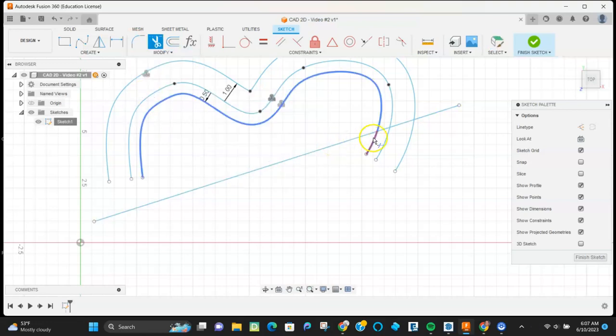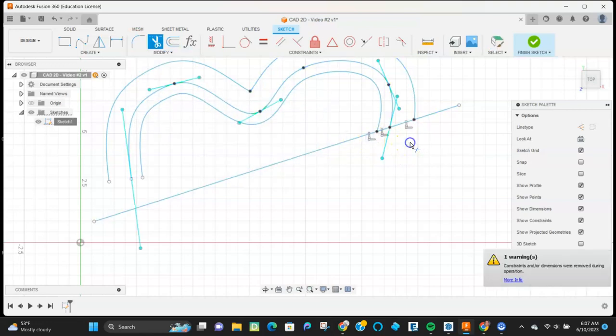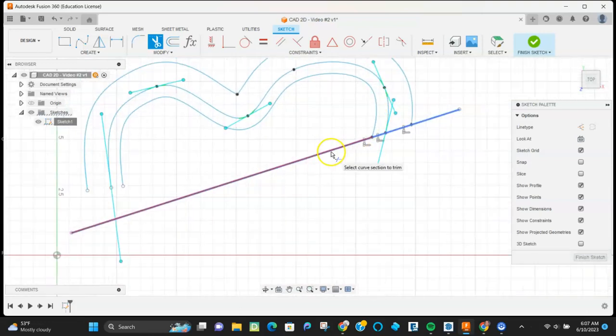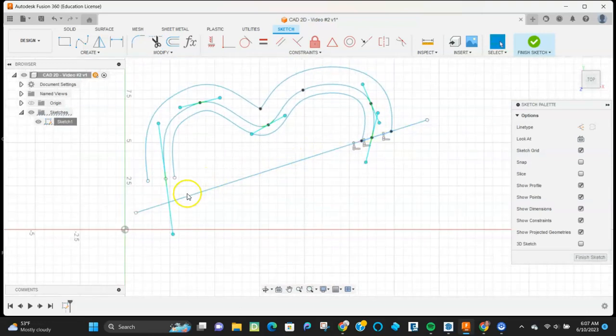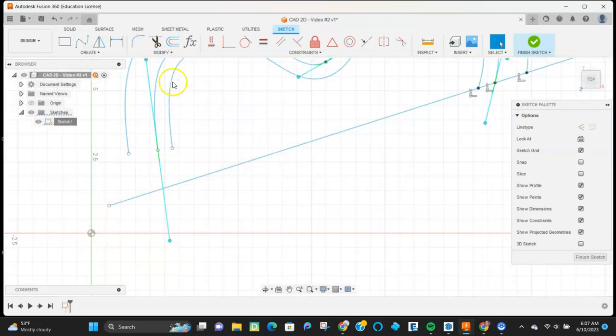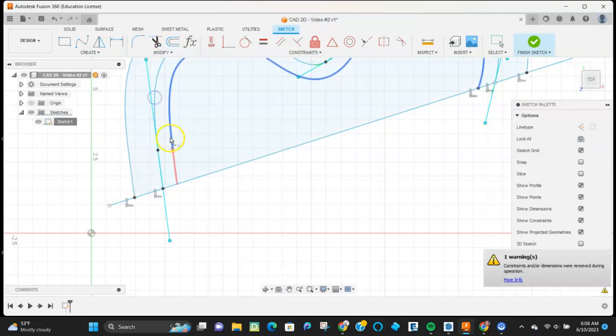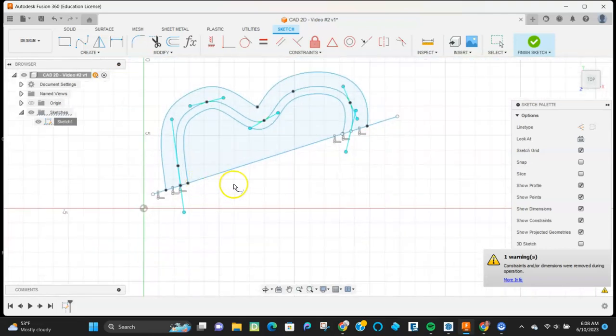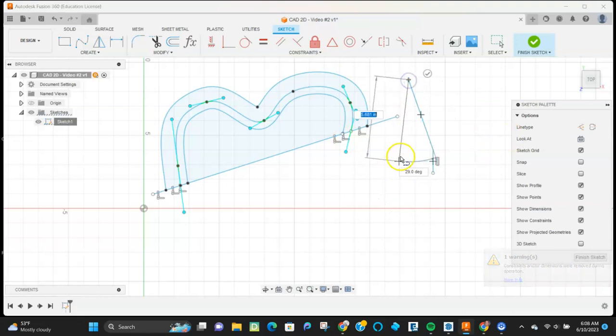So I look and I have a trim, which is basically this cutting shape. So you think about those lines as blades, where if I click on a point, I can cut it at that point of the line. It's again a really powerful way to trim values as they overlap. I can also extend if I want to bring a line to another line, and it will extend that line so that it meets the line that I've set it as.